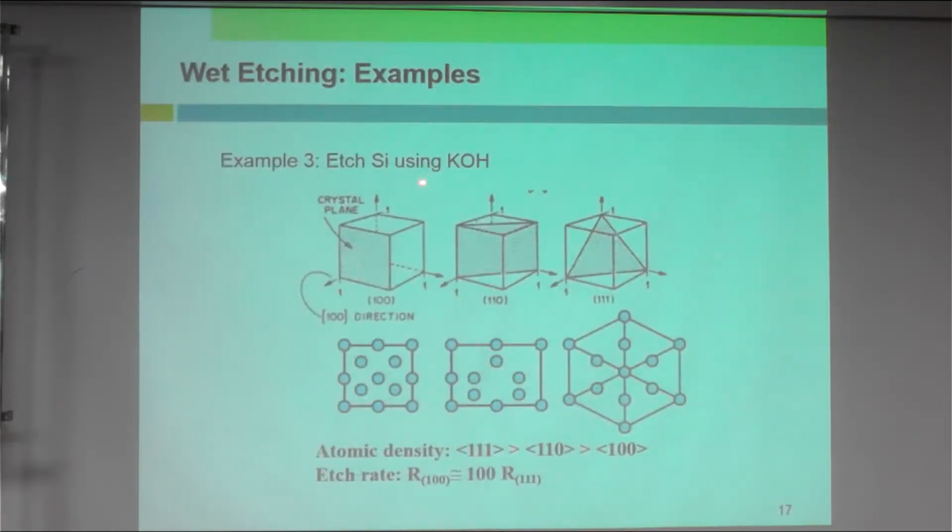So this is the wafer orientation, crystal orientation: 100, 110, and 111. Due to this orientation structure, the etching rate of the silicon will be different. So you can attack the surface of a certain orientation more and others less; there is selectivity for the orientation of the crystal.